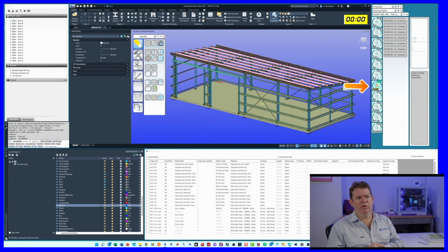We will put those onto an A3 sheet, but we group them by the material type. So we will have a group of mild steel, stainless, aluminium. So you can have that group in the drawing set that you might give to a specific fabricator who specialises in aluminium or stainless or mild steel. So it doesn't put all those items throughout your set. It groups them together in an area which makes it easier to grab and find.